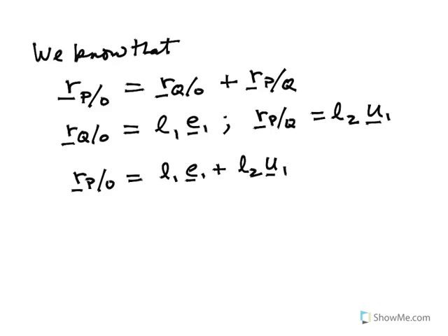And the reason is because the observations of point Q, if you notice, we've expressed the position of Q relative to O, which defines how Q is ultimately going to move, in terms of a basis that's fixed in the first arm. And we've expressed the position of P relative to Q, which is going to define how P moves relative to Q, in a basis fixed in the second arm. So we're going to apply separate transports in each one of these pieces, and then we're going to combine the results to get the velocity.